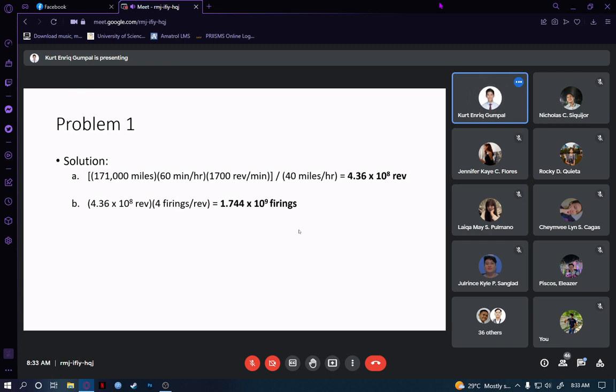Okay? Because you have one fire per 4 strokes. Sorry, I made a mistake there. So that is 4.36 times 10 to the power 8 revolutions times 4 fires per revolution.